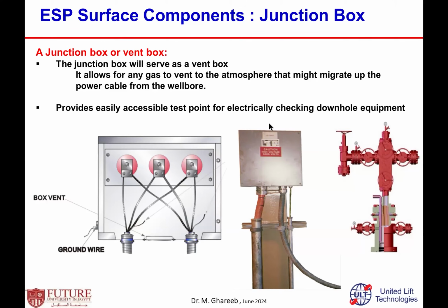It's a very small amount. You cannot feel it, you cannot see it, but it's dangerous to allow the gas to pass with the cable to the control panels or other parts at the surface, where it can meet a spark and cause an explosion. It allows any gas to vent to the atmosphere before it migrates along the cable to the surface electrical connections or electrical equipment.